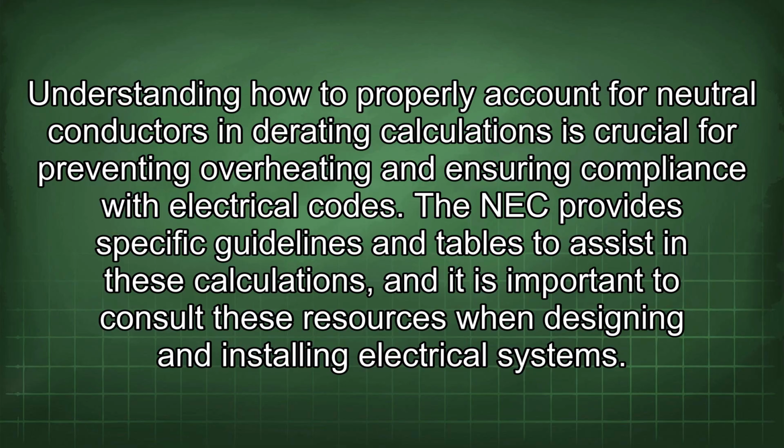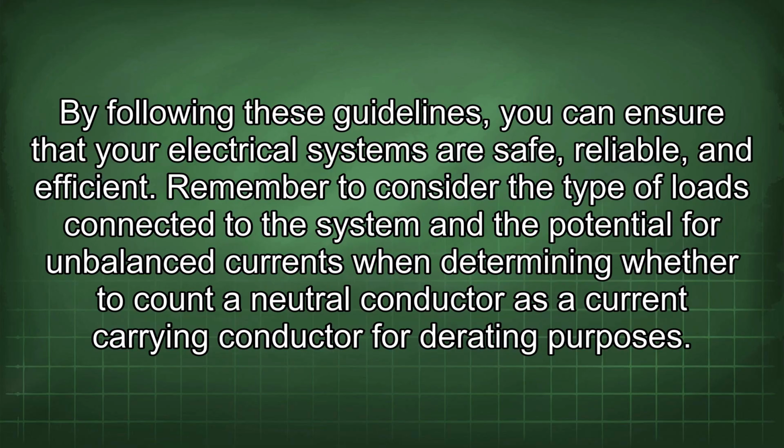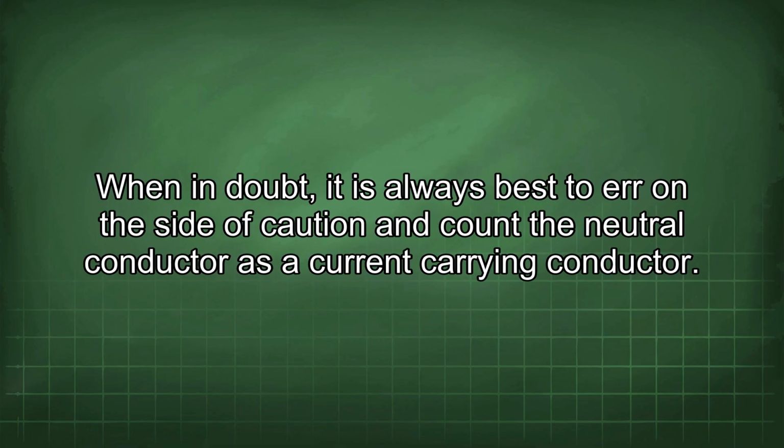The NEC provides specific guidelines and tables to assist in these calculations, and it is important to consult these resources when designing and installing electrical systems. By following these guidelines, you can ensure that your electrical systems are safe, reliable, and efficient. Remember to consider the type of loads connected to the system and the potential for unbalanced currents when determining whether to count a neutral conductor as a current carrying conductor for derating purposes. When in doubt, it is always best to err on the side of caution and count the neutral conductor as a current carrying conductor.